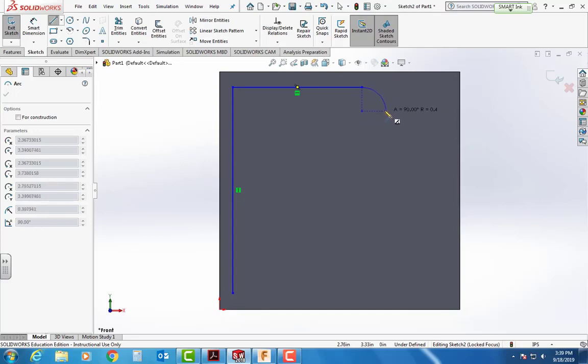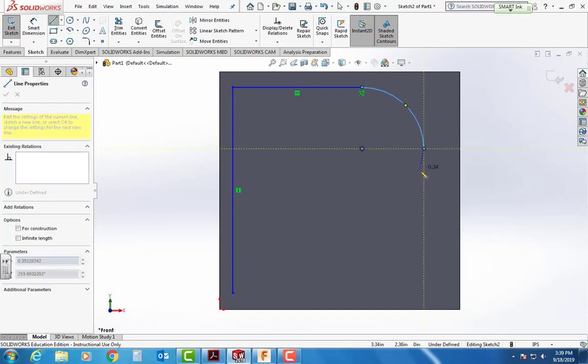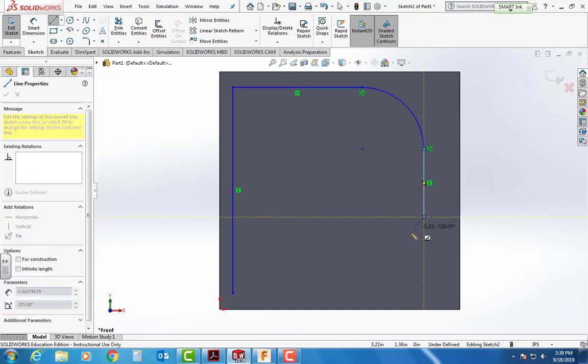So notice how I have my solid dot lines. So if I go too far, that's not going to work. So I want to keep it with those dotted lines. Okay, now it doesn't matter how far you put it. I usually try to keep it within the material. And then I'm going to left click again, and then I'm back to going straight. So I'm going to click again, come away from it. I got a radius right here, so I'm going to come back to it.